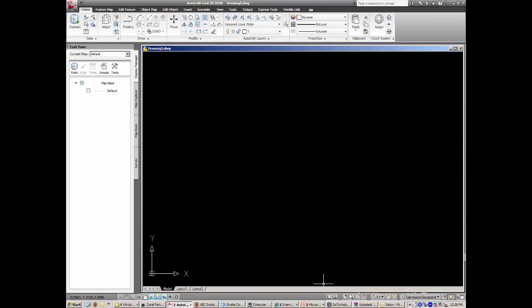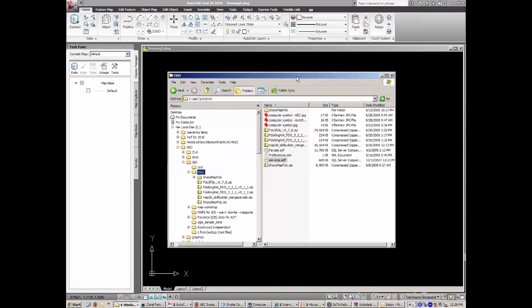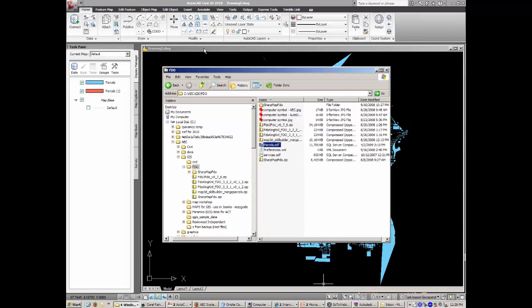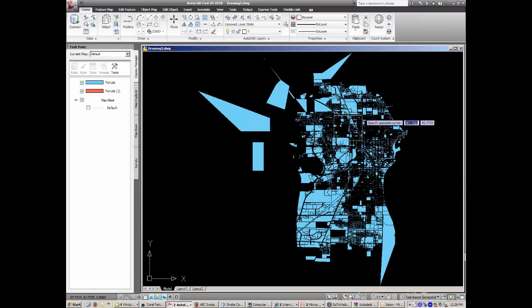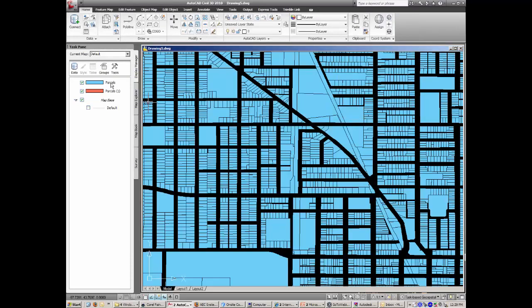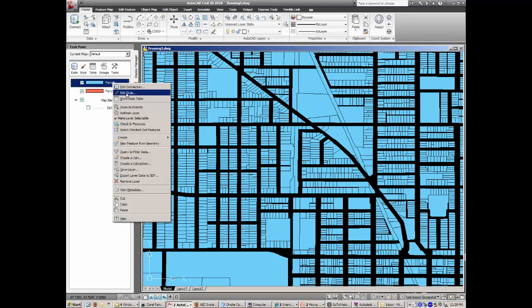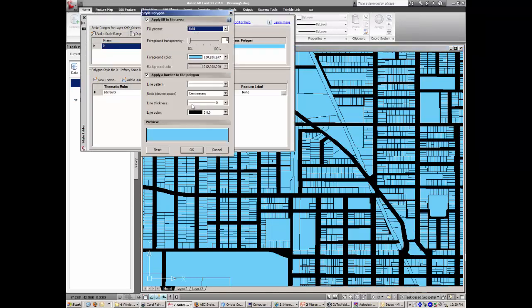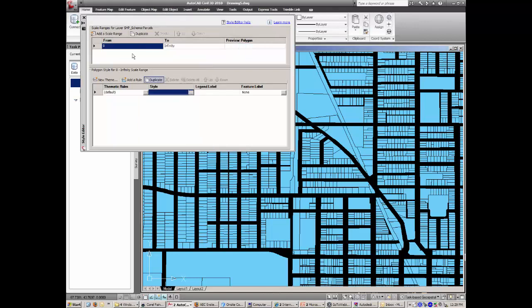Now, what we can do here is the following. We can add a data resource twice. This is a bit strange, coming from an AutoCAD background, but I can pick my parcels resource. I can drag it in here, as I had previously. Then I can do it again. Now, you wonder, why would I do that? Let me just show you the reason. So I'll zoom in here, and I'll go to my first one. I'll edit my style by right-clicking, and I'll remove the fill. I'll keep the border. I'll make the border, we'll say, grey. That's just some aesthetic controls.